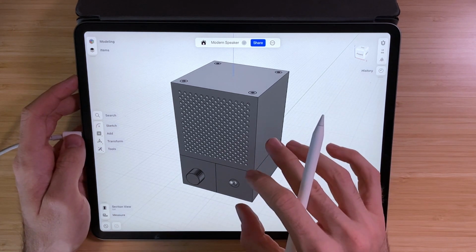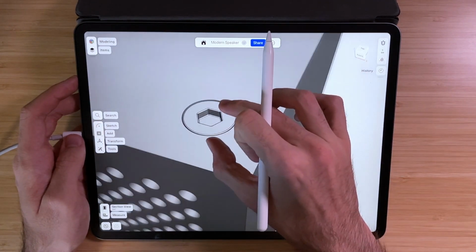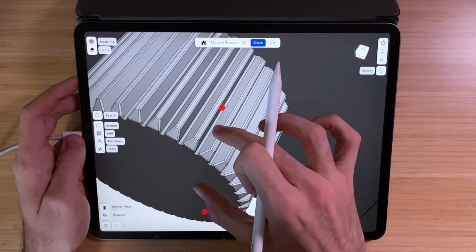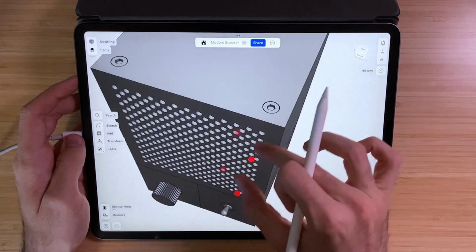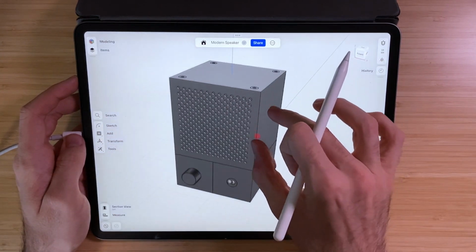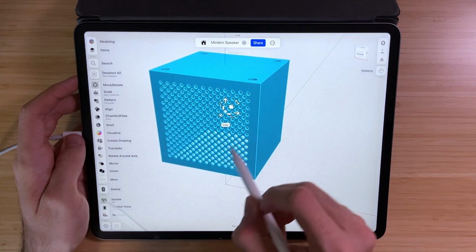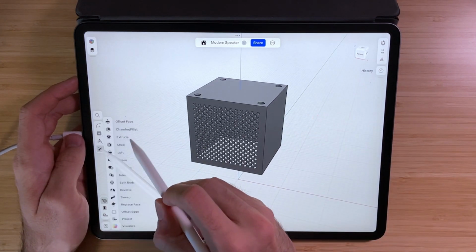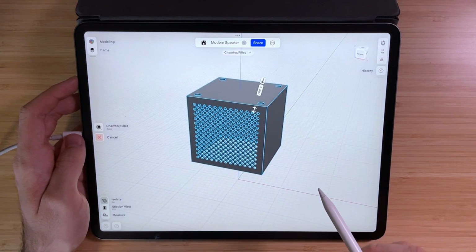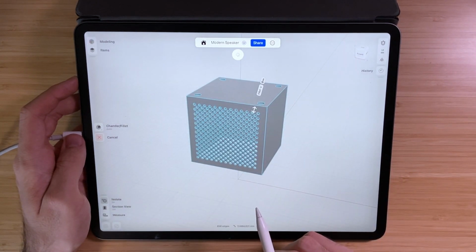Let's put some final touches. We already have put some small radii on these detailed parts, so the rotary dial and then also our screws, but the rest still has some hard edges. So let's do the same thing, isolate one of the parts, then go to Tools, Chamfer Fillet, and then select every single edge, and we'll create a 0.2 radius or fillet onto all of these edges.